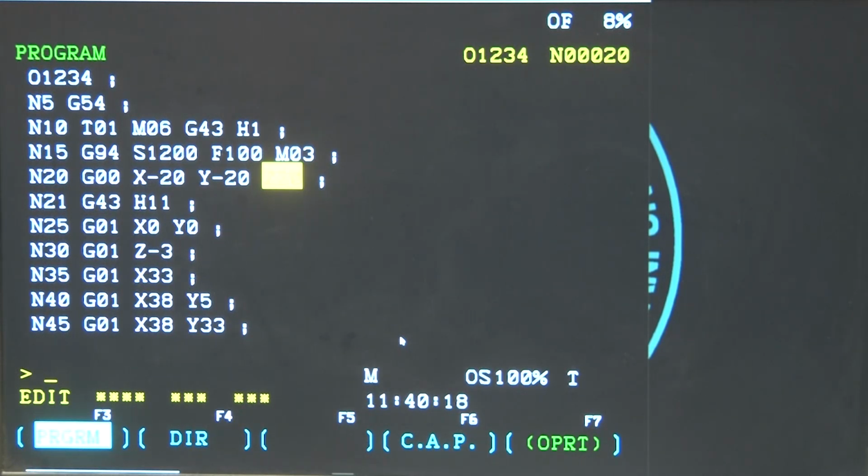So, if you remember, initially I told you that the difference between the NC or computer numerically controlled machine and the conventional machine is that in the CNC and NC machines we have an individual prime mover or motor along each axis, that is X, Y and Z, which can be given movement individually. So, therefore, we can have different kinds of relative movement between the tool and the workpiece to generate various surfaces. That is the basic difference.